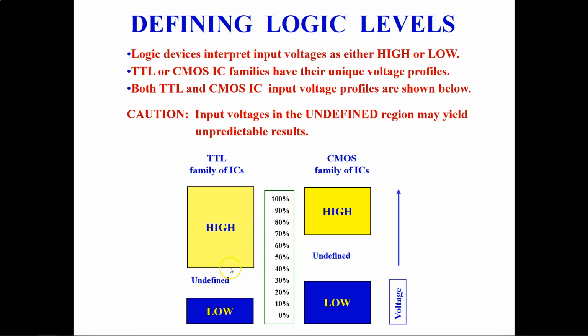So for example, if a voltage signal ranging between 0.8 volts and 2 volts were sent into the input of a TTL gate, then there would be no certain response from the gate, and the signal will be called undefined, or an invalid state. The output signal level ranges are narrower than the input signal level ranges.